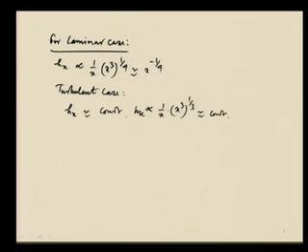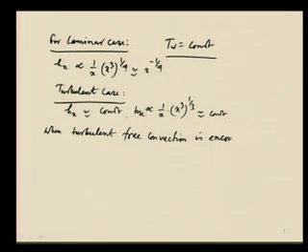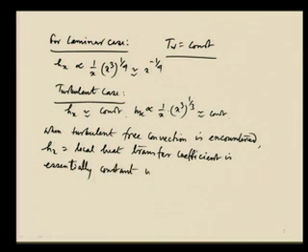Therefore, what we can say is that when turbulent free convection is encountered, this is the case for laminar and for turbulent, under the constant T_w situation, then the local heat transfer coefficient h_x is essentially constant with x. So, this is one very important understanding that we should have.